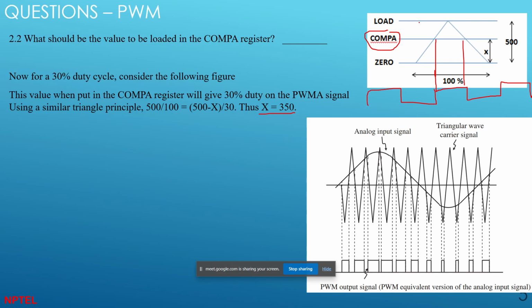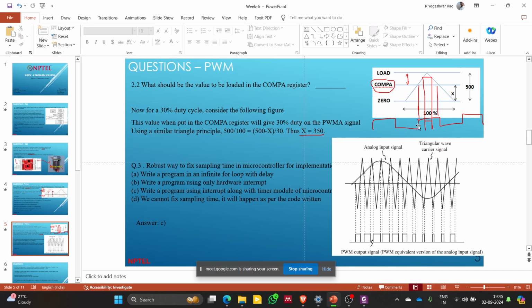So when you change this from 30% to 20%, you see the pulse changing here. The pulse width is this one. It's very small. As the duty cycle decreases, the pulse width also decreases. It's all about this. This is how the microcontroller does the programming in itself.